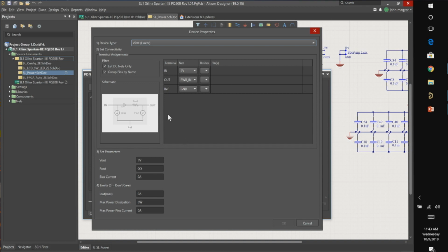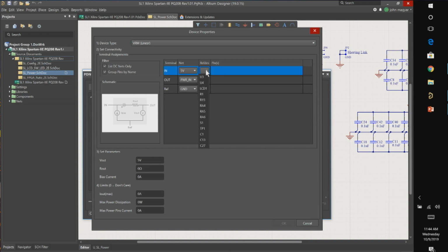You see a little image here. And it's actually going to look at this model and consider the input, output, and what's happening in a typical regulator. So now I'm going to specify the actual load instance. So this is U4. I'll show you this in the schematic when we go back. And U4 is supplying the 1.8 voltage, which is the internal core voltage, or VCC internal. And then we have ground. So these are the three signals we have to connect.